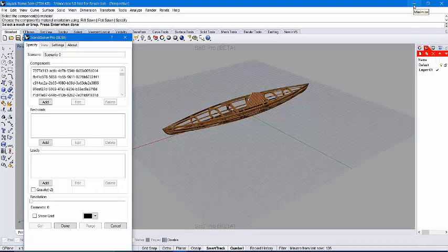So one person asked whether the only orthotropic material is wood. Currently, the only built-in orthotropic material is wood, but we will be adding support for composites later, because I assume that's the question you're really asking. For now, you can actually enter a composite material as a type of wood. You can sort of fake Scan&Solve. It doesn't know the difference. Internally, it operates the same way. So we'll give it just another 30 seconds to see if we get any more questions in before we continue on.